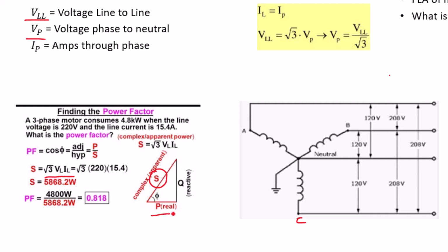The real power is actually the amount of power that is consumed by the equipment. So that's also represented as watts. So the complex power S is represented by VA. And when the equipment uses power, that's actually the real power that it's using, and that's represented by the watts. And the reactive is the third part of that triangle. The main point of this is that the current that is flowing in the wire is going to be represented by this VA.